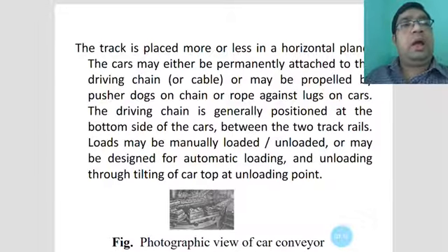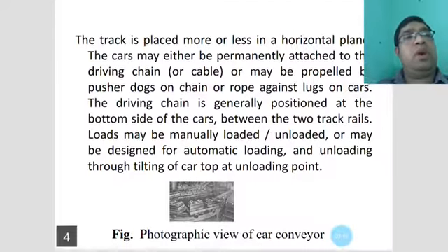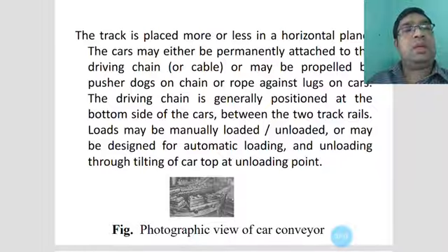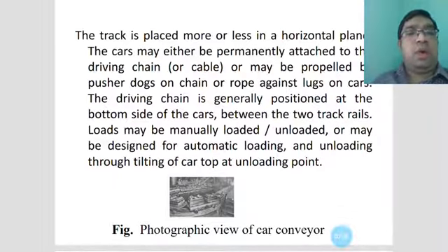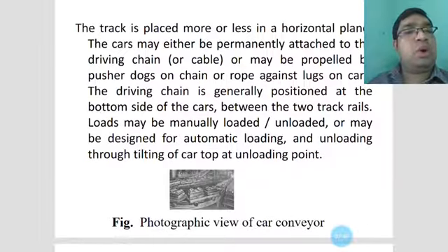In small scale industry the loading will be manual, and sometimes you can see manual labor will be reduced due to the car type conveyor, in the transfer of materials from one place to another place. All things also will be considered according to the design process of the car type conveyor, and which type of conveyor system you choose, either automated or manual, depends on the design.